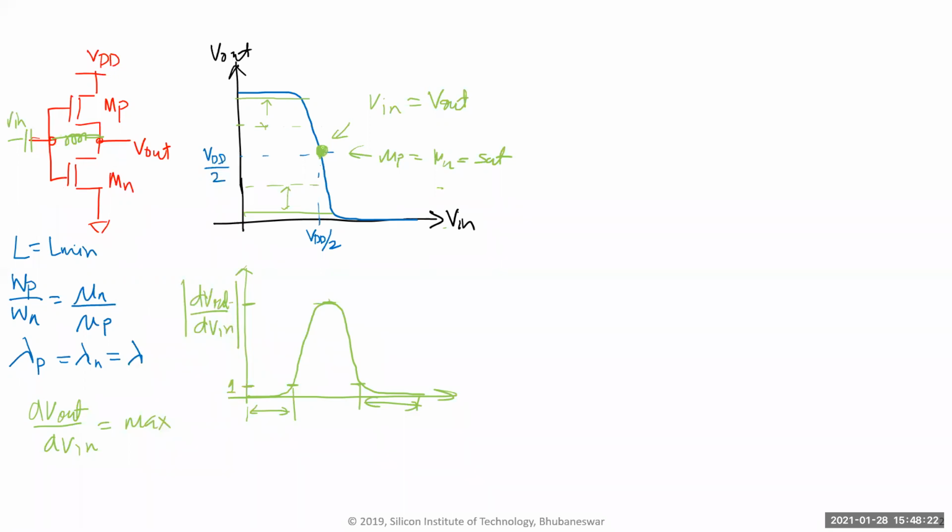Okay, so if I put a big capacitor and a big inductor, then at DC it'll come and just sit there, because the inductor will actually short the input and output. But once I put a small signal in, it'll allow it to go through, because it'll allow an L di over dt, right? V equals L di/dt. So there is a small current, there'll be a small voltage across it, right? So it'll allow this.